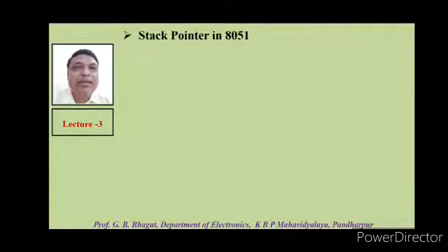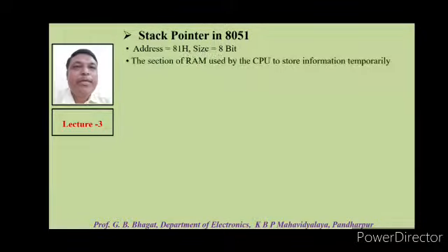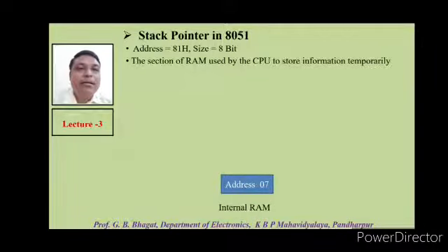Next, let us see the stack pointer in 8051. The stack pointer has the address 81H and its size is 8 bit. The section of RAM used by the CPU to store information temporarily is nothing but the stack. This stack has the default address 07 in internal RAM. That is, by default the address of the stack in RAM is 07.